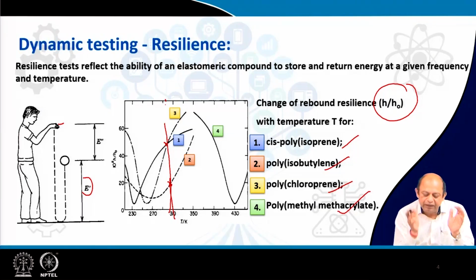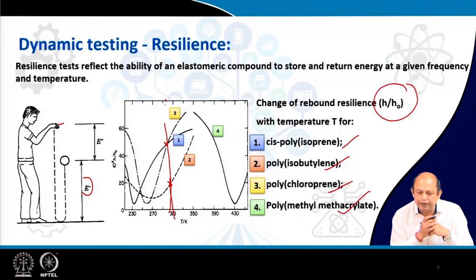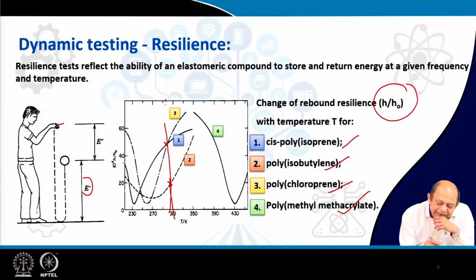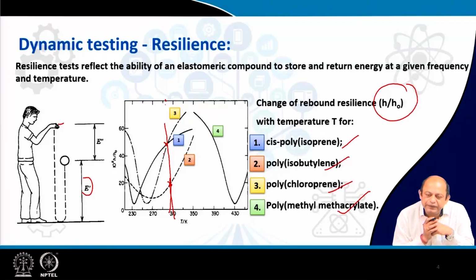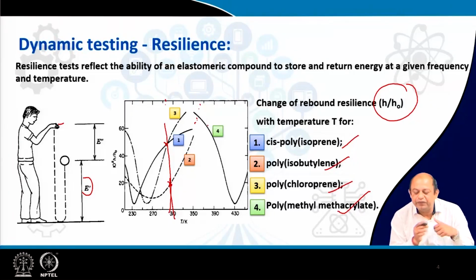You can see the butyl rubber has obviously a low damping or low recovery as compared to polyisoprene and polychloroprene rubber. But if you look at the trends of the curves, you see butyl is going upturn. So if you increase the temperature, there is every chance that it will cross polyisoprene, which is considered to be one of the most resilient rubbers in general.